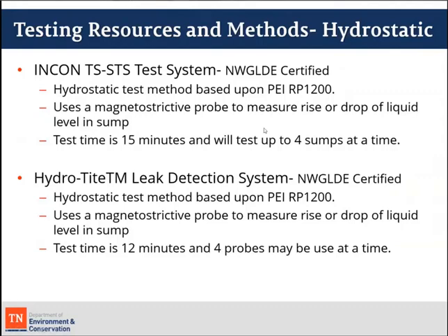They all use a magnetostrictive probe to measure the rise or the drop of the fuel level in the sumps. The test times vary a little bit. The number of sumps that can be tested may vary a little bit. But as you can see, the test times are on average much quicker than an hour.